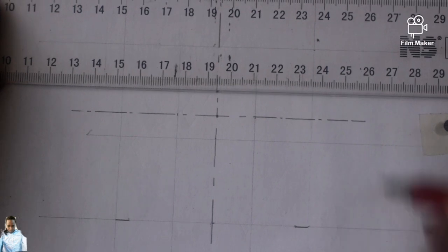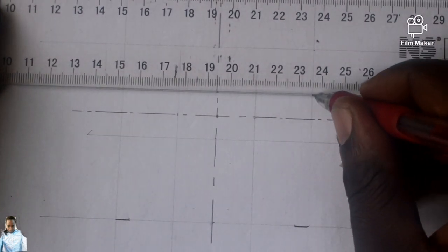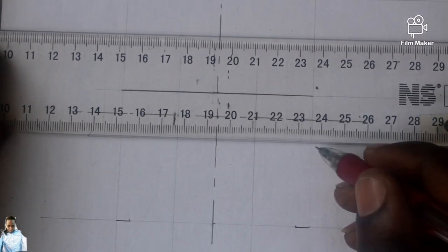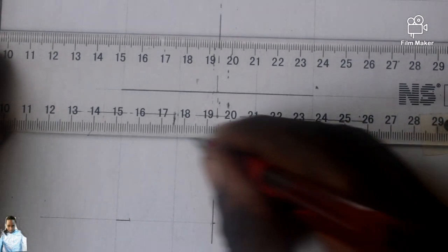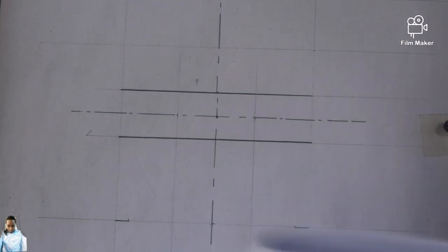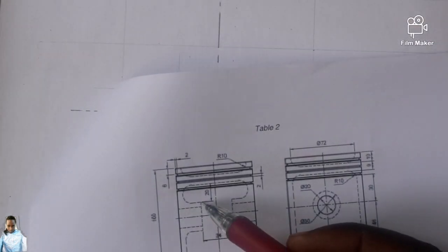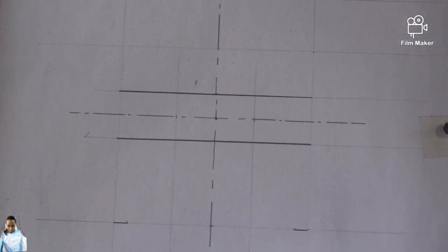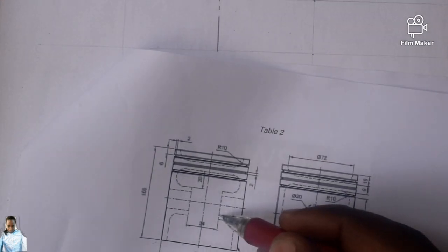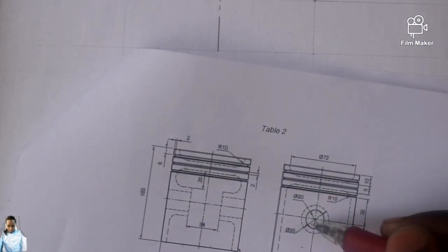So from here till there, the moment I'm drawing it dark throughout like this, I'm considering item 2 as well. Because if item 2 was not there, this dark line was going to end here, which is this one. So now from here till there is diameter 30.